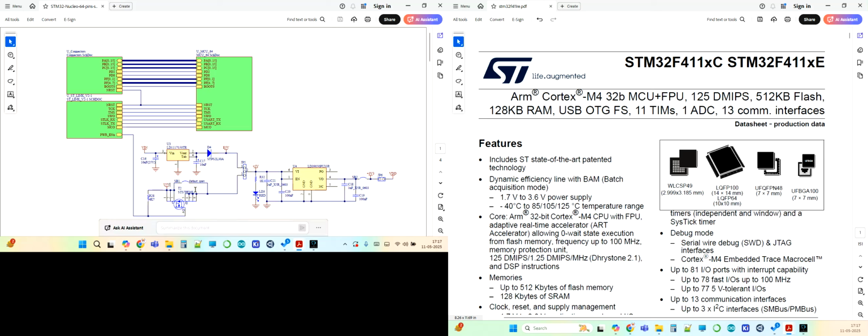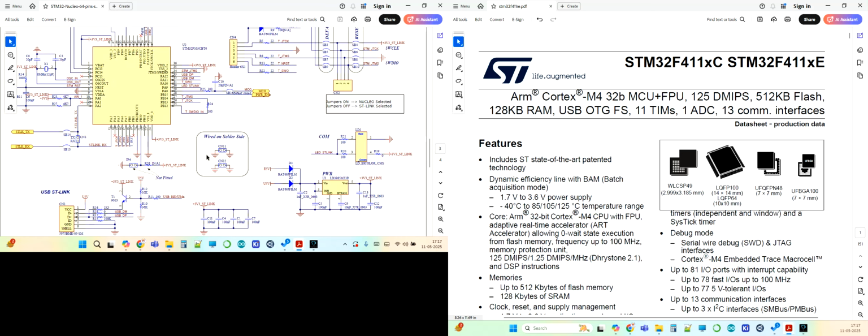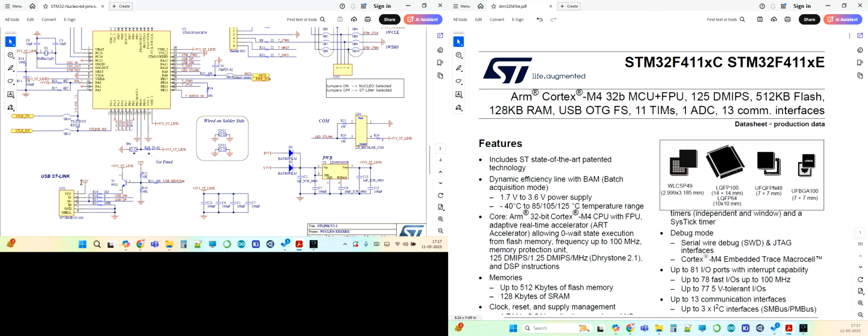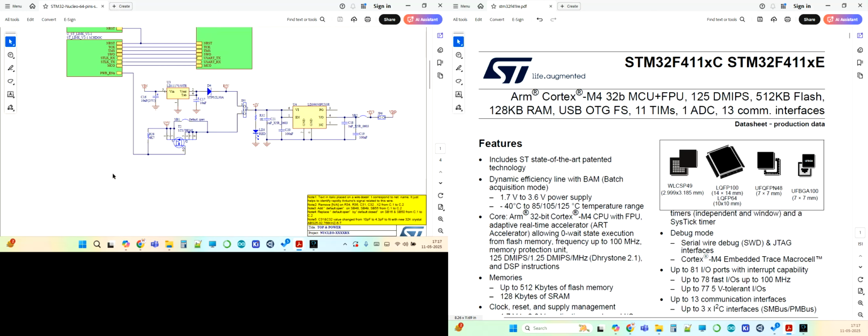Where are we generating this? If you see U5V, let us start with this U5V. U5V is actually coming from the USB connector where you plug in the ST-Link USB cable to power this Nucleo board. So the power to your board starts from this USB. As you all know, only when you plug in do you get the power, right? There is 5 volts coming from your laptop or the computer which you connected, and that 5 volts comes through this MOSFET to here, and in JP5, pins 1 and 2 must be shorted. You can check your board: 1 and 2 will be shorted, the third will be open. So this jumper will be placed and you get the 5 volts, and this further generates the 3.3 volts.